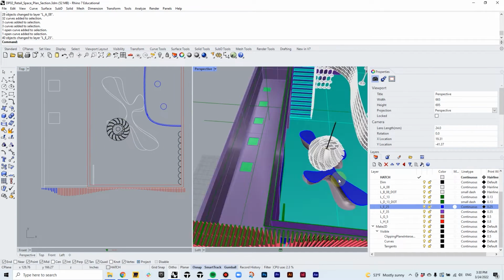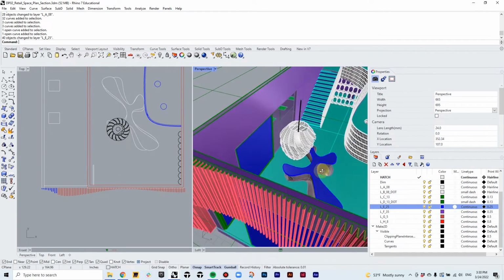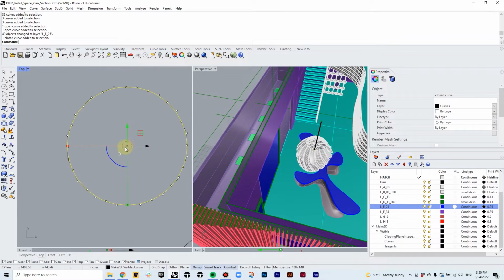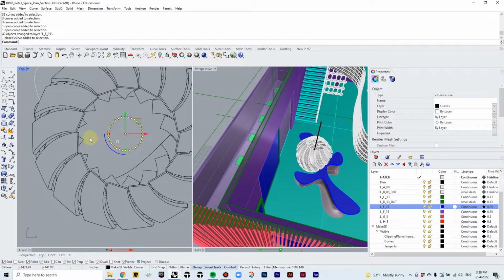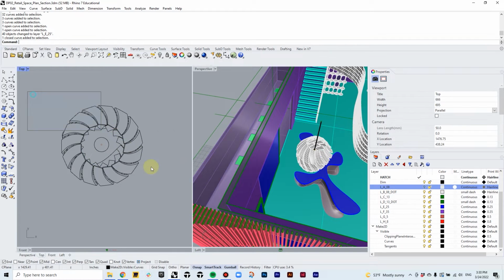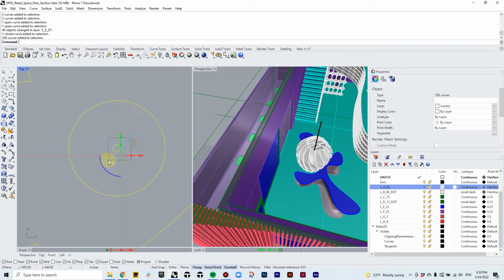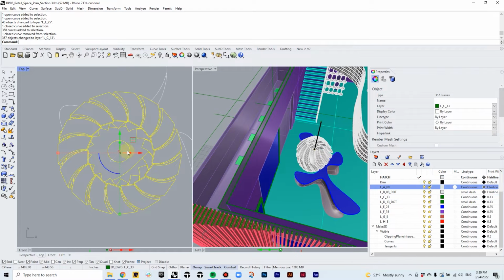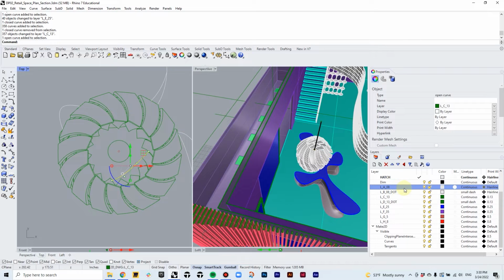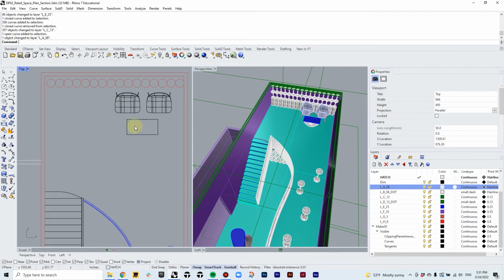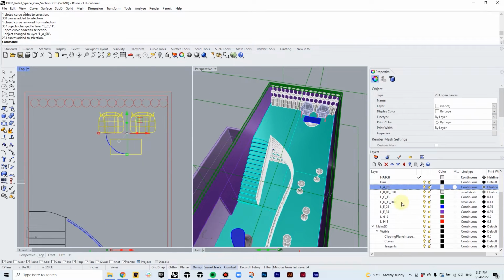This chandelier, maybe they are 0.213. Oh, but there is indication of section cut of the cable, so that's good. So in this case, I'm just going to turn off 0.8 layer and then select everything except for the cable, and then change it to 0.13. Turn it back on again. This one actually is a table line. So that is that. These chairs and tables, they are pretty close to the view, so they can be 0.25.